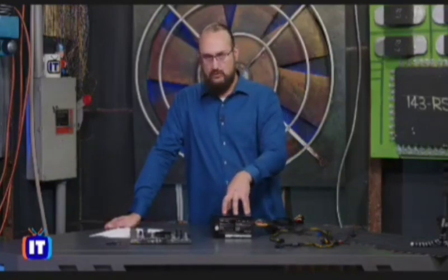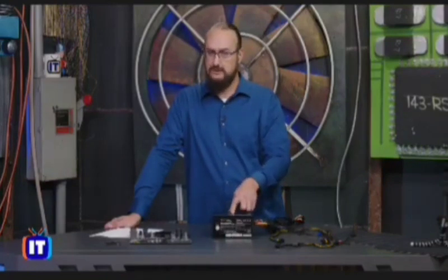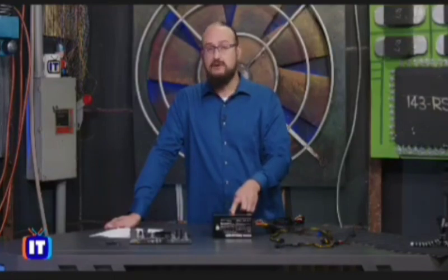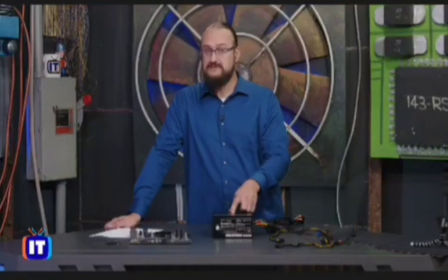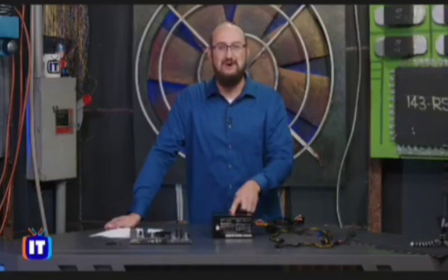So let's talk about that real quick so we understand that if I flip this to a 220 circuit and I put it on a 115 circuit, I'm going to be grossly underpowering my system, and that's going to cause system instabilities. However, if I switch this to a 115 circuit and I connect it to a 220 outlet, I'm going to fry the power supply and all the components there.